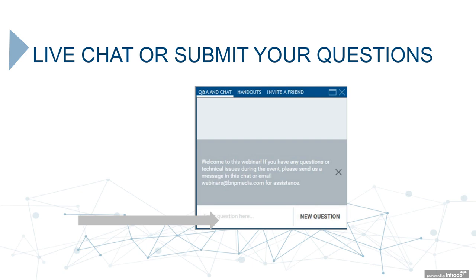So when you're likely to be asked about this is, it probably comes up at the design stage, but it also is going to come up when the panel build is happening, especially if you're a UL 508A shop. At some point, there's going to be an audit or an inspection of your project, and this may be one of the things that the electrical inspector asks you about. What's the rating on this cable? Can you tell me the insulation voltage rating? If it's marked on there, they can read it clearly and they can move on, or they may ask you for paperwork on the cable to verify what that insulation voltage rating is. So that's when it's likely to come up. Okay.